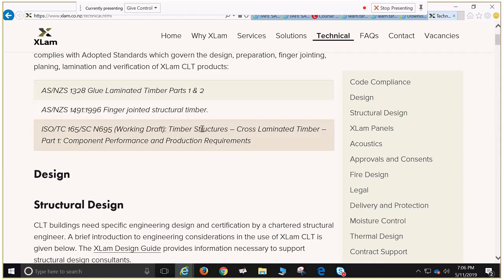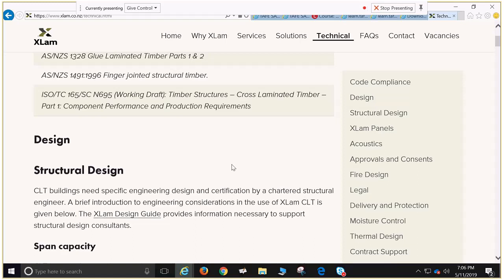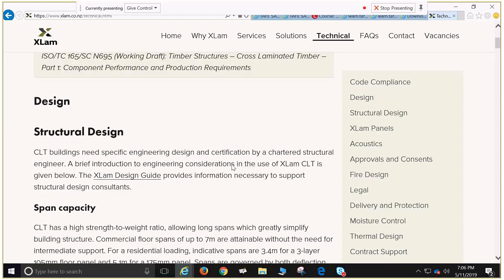and timber structures, but not one that relates to building with CLT, as you would have with AS1684 for timber that says if you do this it will do this. Might be worth trying to come up with a British standard actually. But I think for your design and implementation, it's probably better to go directly to the manufacturer's resources. Absolutely. You're obviously not going to make your own cross-laminated timber at home.